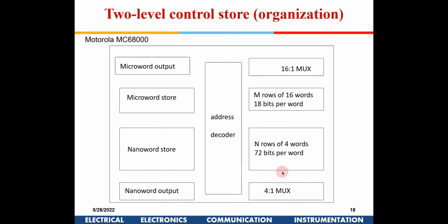If you organize the memory in this manner, you can use decoders, which are generally AND gates, with a small fan-in, that is, a small number of inputs. So the decoder becomes faster, power efficient, and simple in design. Why that happens, we will look into in detail in the memory organization class.